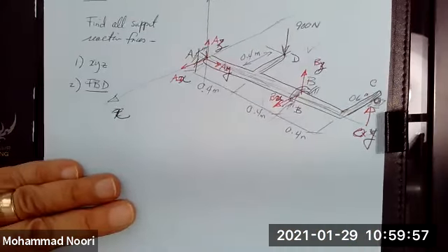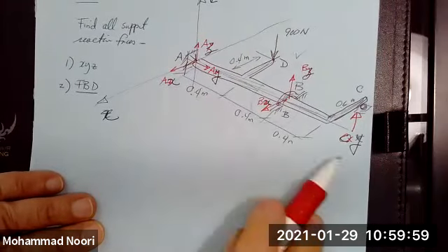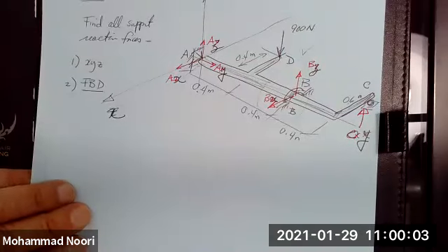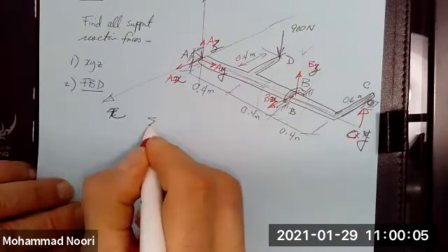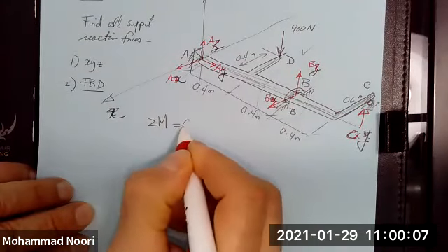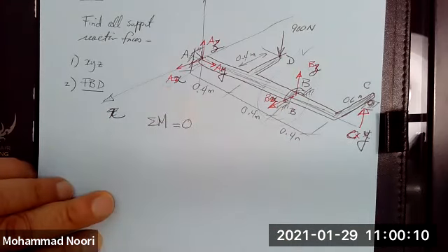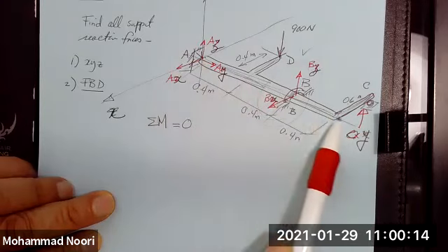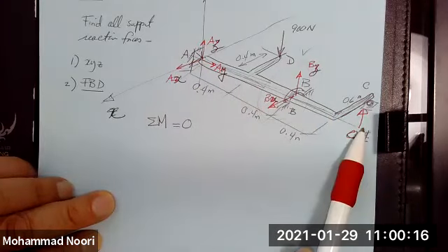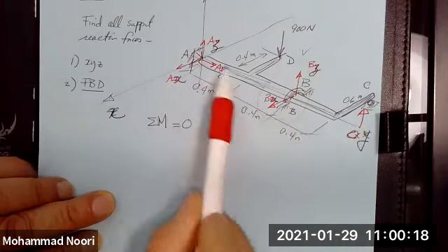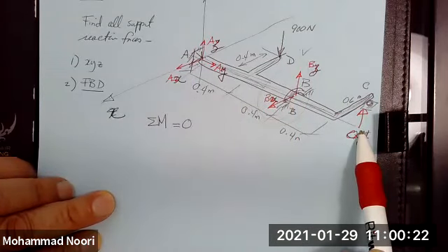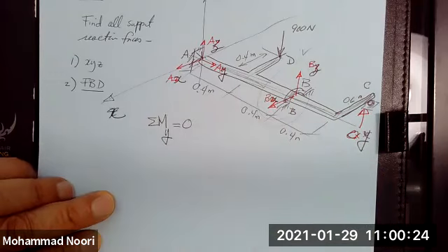All right. So if I want to solve for the unknowns, you can quickly see in this problem that the summation of moments about an axis is the best. And what would be that axis? Look at the y-axis. See? These forces all intersect with that. So the only unknown you have is Cy. So I'm going to take summation of moments about y.